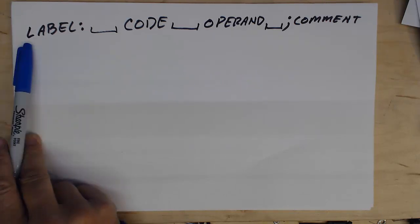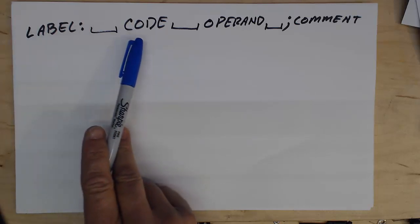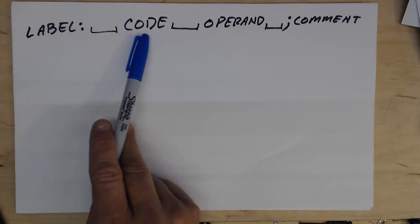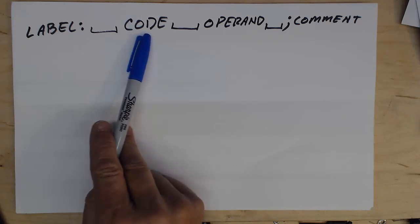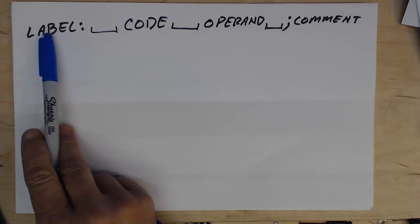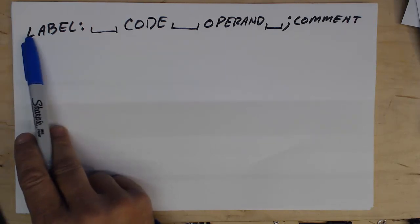So the assembler will probably allow the first character in the label to be anything other than a number. And the label itself can't be from the reserved list, and the reserved list is basically anything that you would find in the code or anything that you would find in an expression. So you can't have, for example, any of the register names, you can't have any of the Boolean logicals like an AND or an OR. Those kinds of things can't be in the label, but there's quite a bit of freedom with what the label can be. Just don't try to start it with a number.